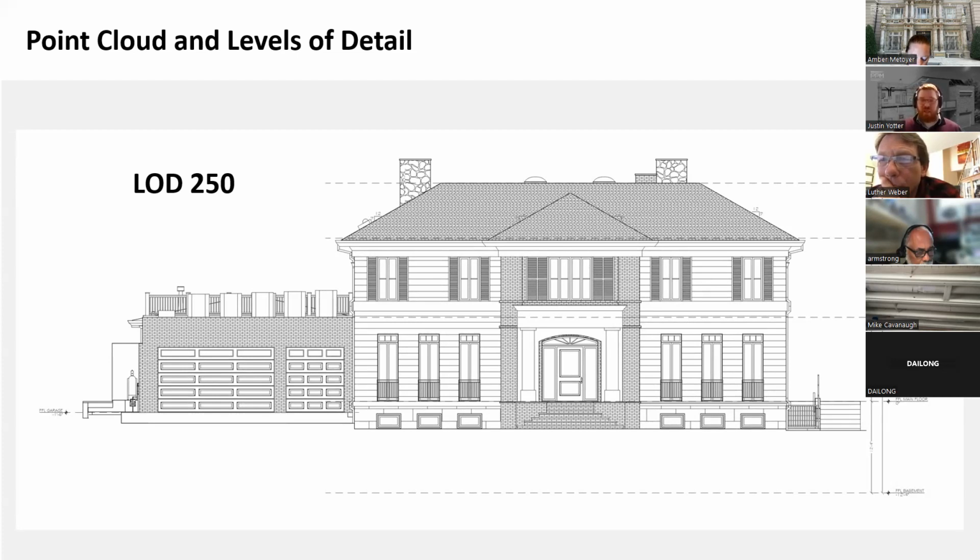Mobile scanners will likely be less time on site overall to capture any of this information, unless you have a lot of scans that require global accuracy, and then what you spend in scanning time, you'll gain back in less complications in the drafting and modeling process. Terrestrial scanners can take hours, if not days longer on site. So where clients or occupants can't provide extended access, the mobile may still be an option.